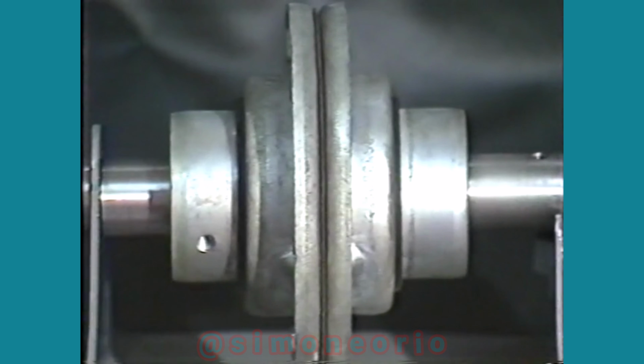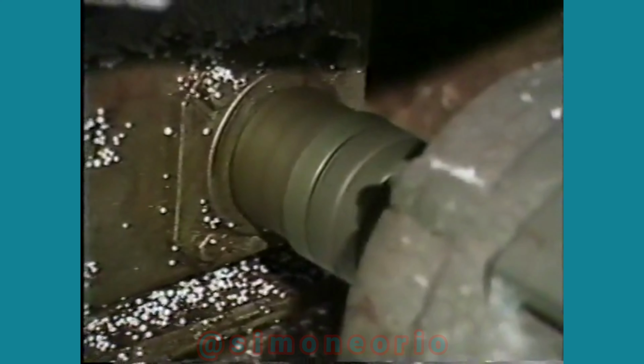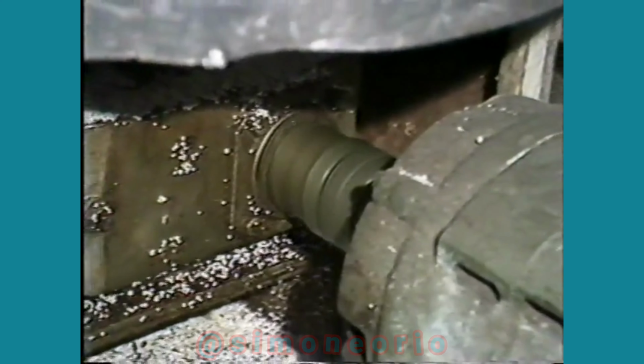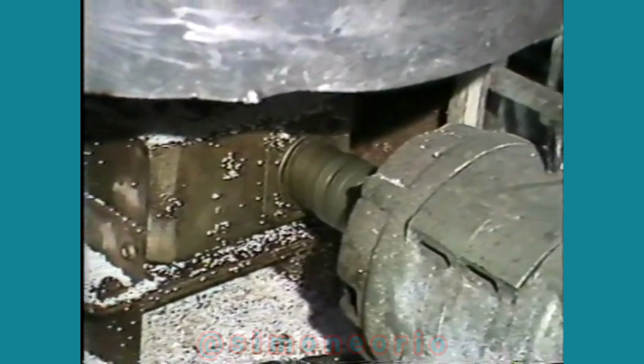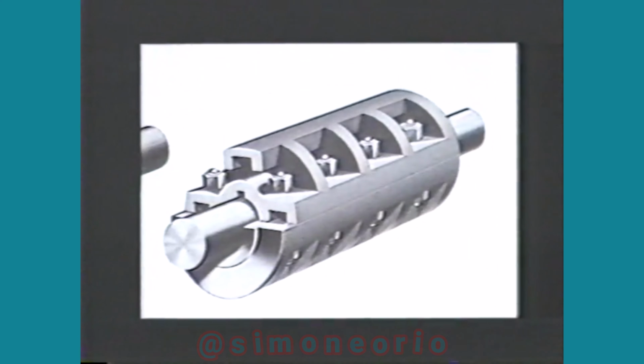Shaft couplings are devices which are used to connect two shafts together. Shafts need to be connected for two primary reasons. First, to transmit rotary power, and second, to extend one shaft by the addition of a second one. When a coupling is used to extend a shaft, the objective is to make the two shafts perform as one.